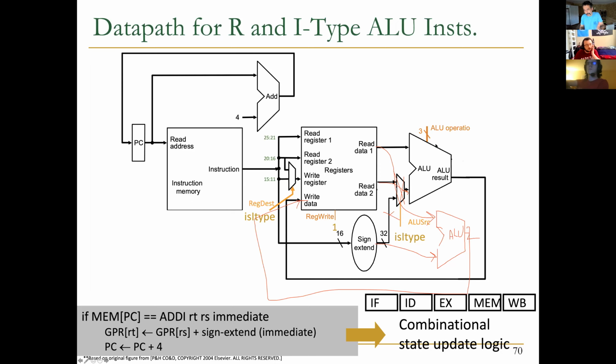So imagine, obviously you need some other elements here, but what I'm asking is, imagine we do all of this. Obviously this implements whatever we want. This implements both R type and I type, with a slightly different control signal, some rewiring, some other elements that we need here, but essentially does the work for us. If you were asked which one you prefer and to reason about performance, how would you approach this? Given that both implement the semantic of both R type and I type correctly, there is no incorrect implementation, right? Imagine that they implement the correct semantic of either of these instructions. Which one do you prefer and why?